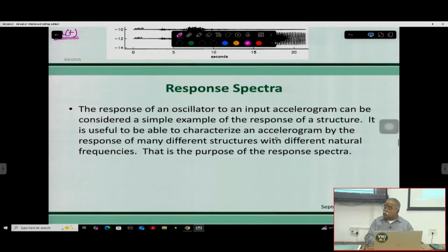That is what you call the building deformation response, meaning how much the building is deformed. So the deformation response is basically the UT. Now you can see this is your UT value at a particular period and particular damping, and this is your time history.